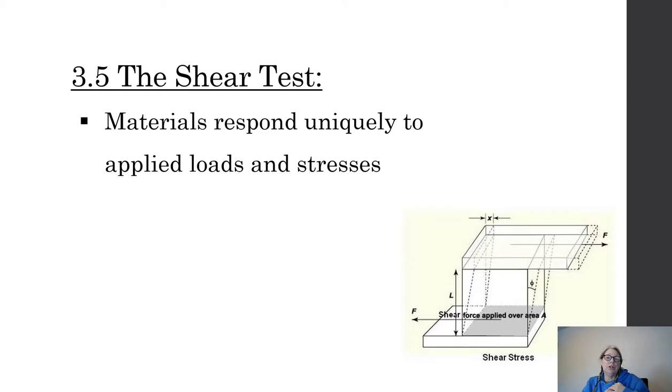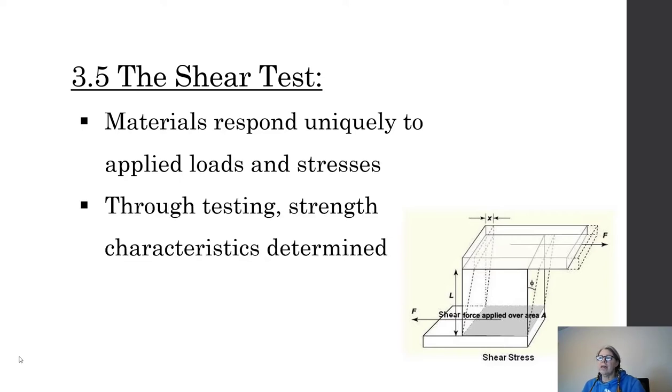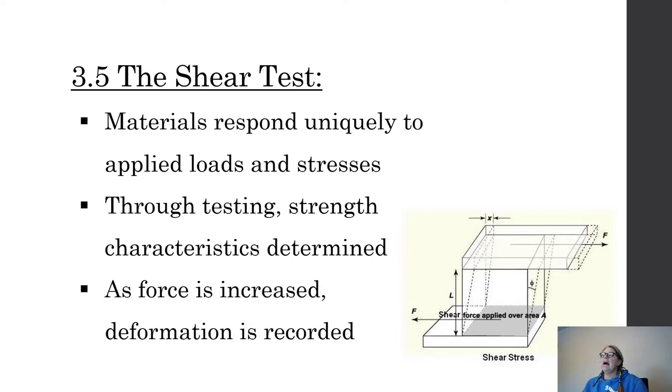We're going to have a shear test. We have to see how they behave when we apply a shear load. So remember, that's a force that's parallel to the surface. Okay, so the force is coming across the top. It's going to be parallel to that surface on the top, and it's going to cause that distortion. And we talked about the shear strain is an angle. So when we have a shear test, we're still trying to determine material properties, right?